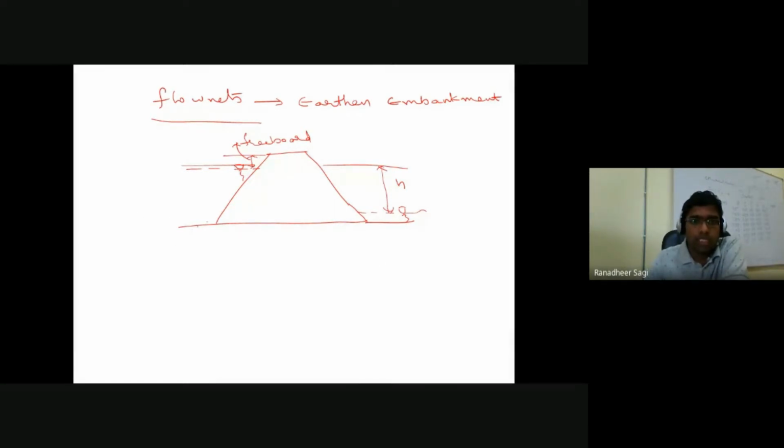So let me consider this is an impermeable strata. I have my embankment constructed on some impermeable or impervious layer. So on top of your impervious layer you have your earthen embankment constructed. Once the earthen embankment is constructed here, and the water storage on the upstream is somewhere here, the water tries to flow through the cross section of the embankment like this. This topmost line I am indicating, I'll be calling it your flow line, the topmost flow line in this particular case.